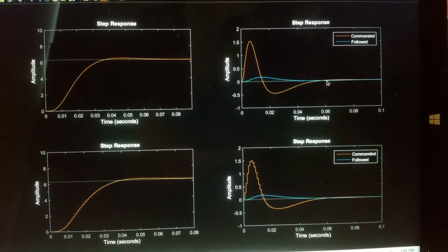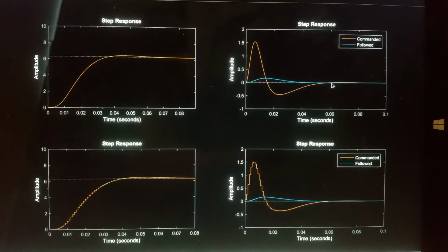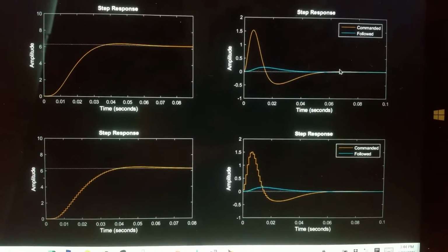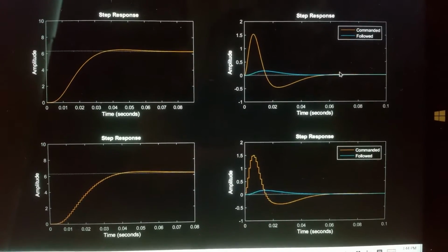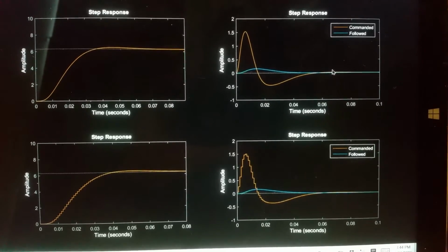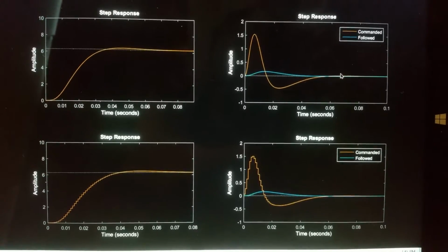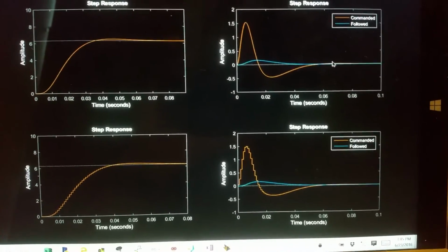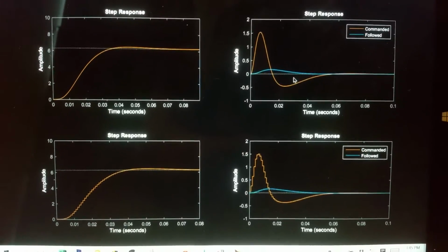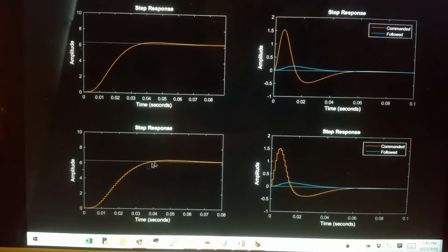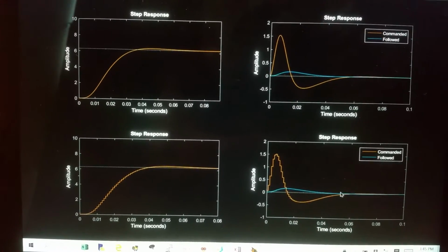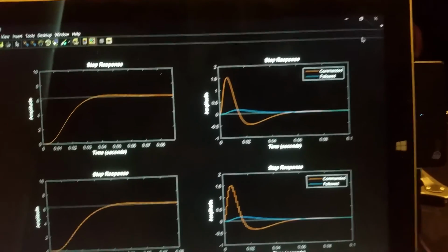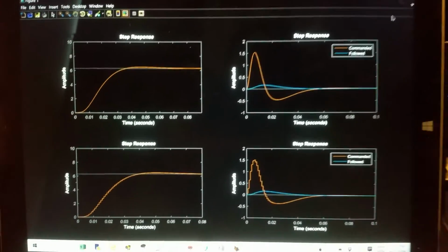So this is the P rate, or your first axis rate, and so you have to send this torque signal to the motors, which is basically just take that torque value divided by 4, and then also divided by the arm length, which is in my case 6 centimeters. Anyway, so I have a discrete version because I have a computer, and sure enough, it looks very similar after applying all the tricks that I've learned. It's very similar, okay? And so what I want to show you next is it actually flying. So I'll do that now.